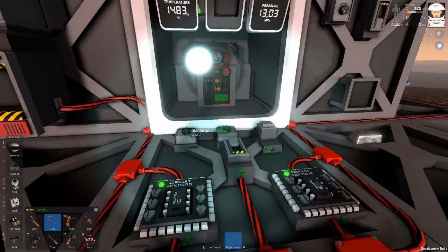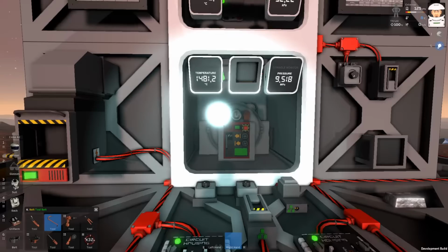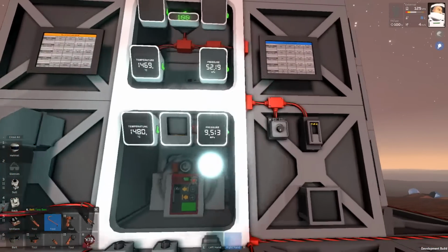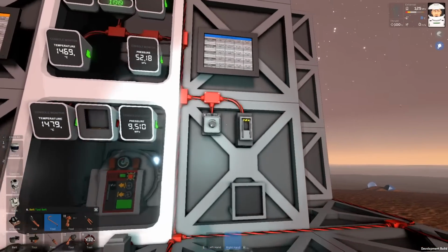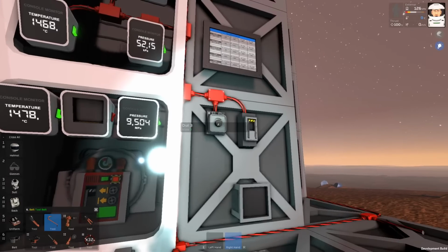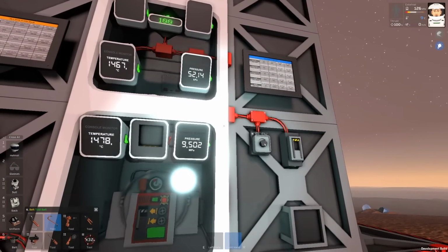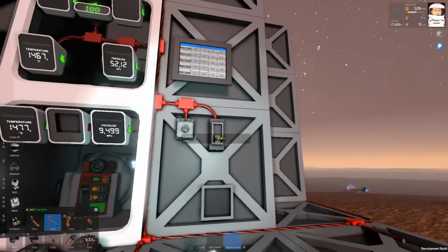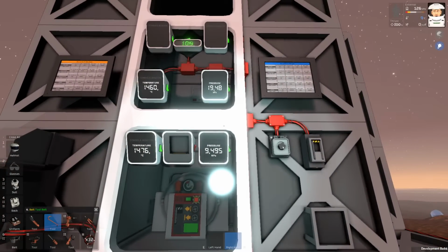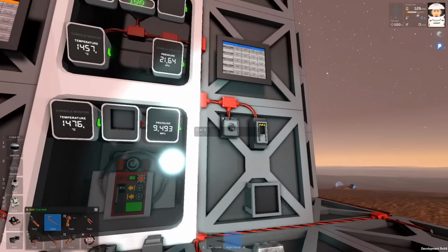So I'm getting ready to stop the valve. So we have almost 10 MPa. Perfect. So I stopped the valve, but now we need to lower the temperature, and it is very easy to do. First, I will pump out the air around the furnace. I will switch this dial to 1. I will pull the lever. And we have the air from the room almost removed.